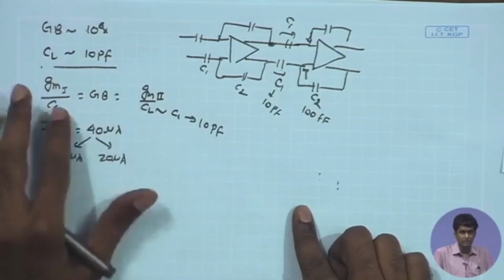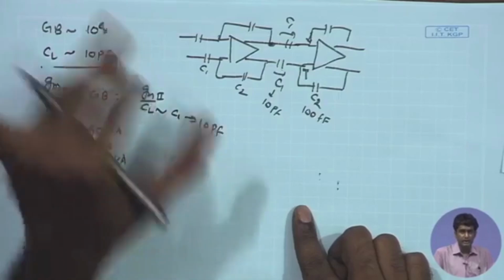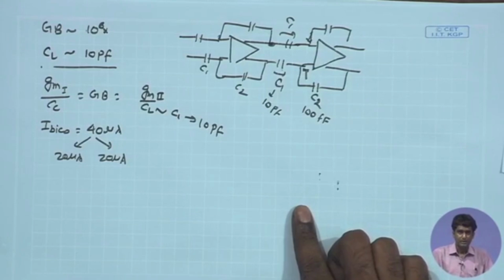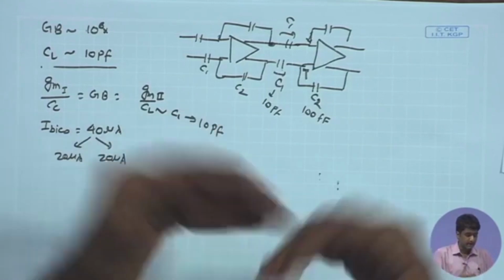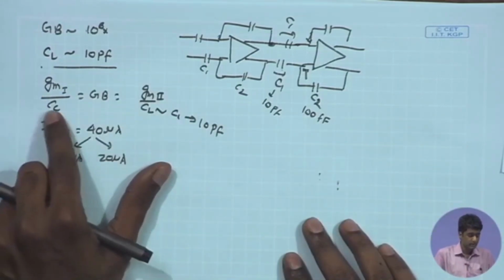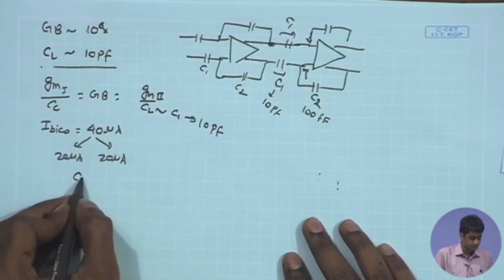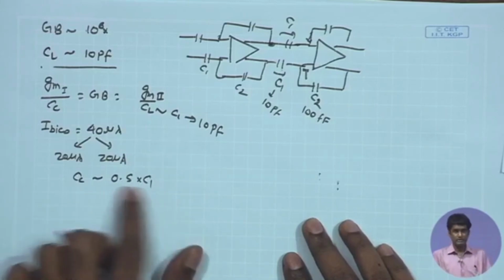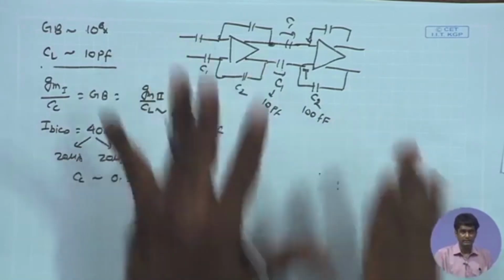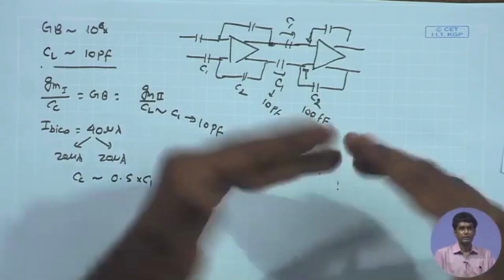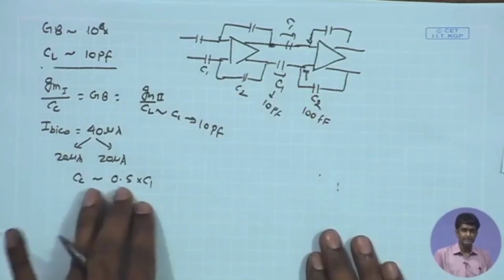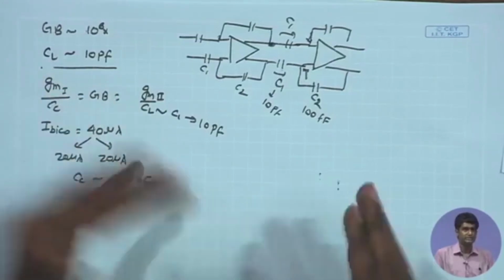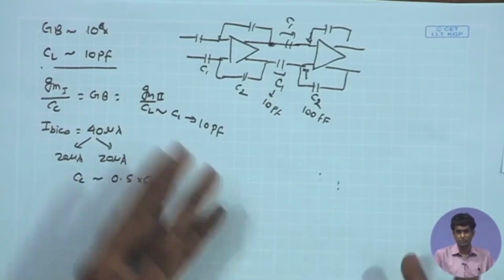If I go a little bit more aggressive, make it 2 picofarad, then of course the area consumed by this CC is significantly less as compared to the C1. So, let us start with an estimate that let us keep CC equal to 50% of C1, so that it is not adding more than 50% area as compared to C1. Definitely one of the important design constraints can be to minimize the CC as well, and that again translates to the ratio of GM1 GM2 and sizing of the GM1 GM2 transistors and so on.